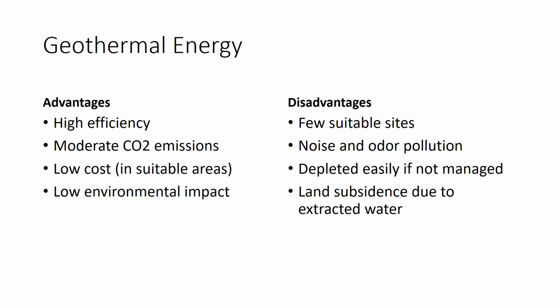It can be depleted if not managed well. And then land subsidence, which is like sinkholes due to extracted water. If we extract too much water and we're taking too much water from the pore space in the soil, then the soil can collapse on itself. So, yikes.